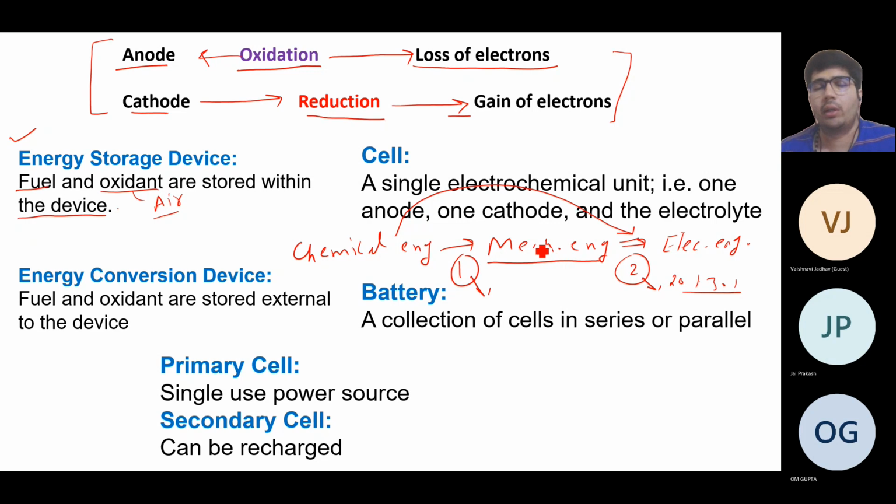Okay, we are using the electrochemical reaction, so we can directly convert the chemical energy to the electrical energy. So the efficiency will be more, because basically electrochemical reactions are there. There is no combustion, because in combustion we know that a large amount of energy is going in the exhaust. Because we cannot get the exact combustion, or the exact stoichiometry reactions in the combustion. So the large amount of energy is going through the exhaust and dissipated through the heat.